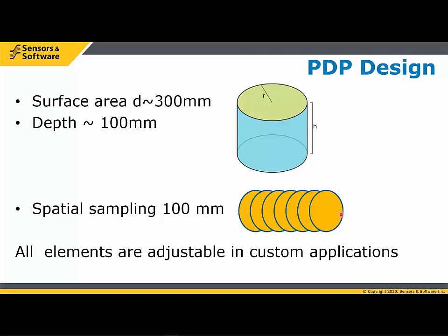I wouldn't say it's unique to the pavement density profiling needs, but it's typical of any set of measurements. I'm sure you could go out and take a dozen cores in the same area and contour that, but how reliable would that be? My confidence would start to go down if my footprints here didn't touch each other; I'd start to get concerned about the reliability of the map. If you have sparse data, then you get into the usual contouring, kriging, statistical approach to how you build your contour map.